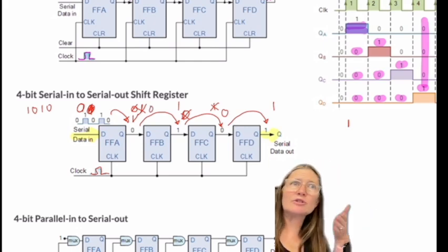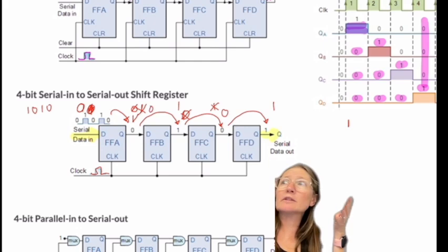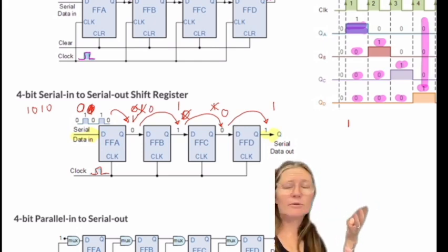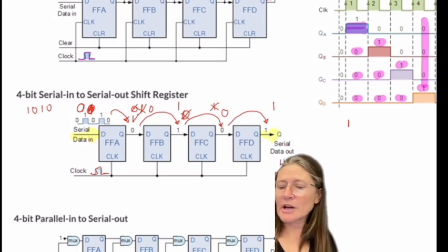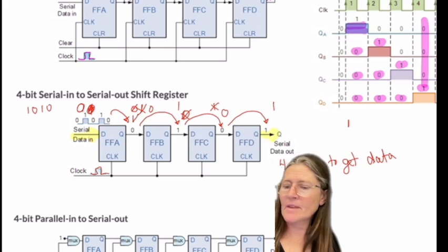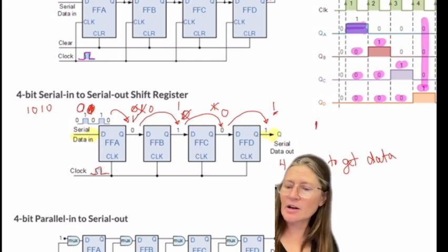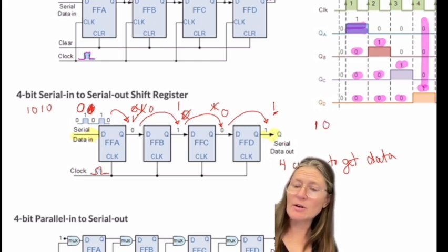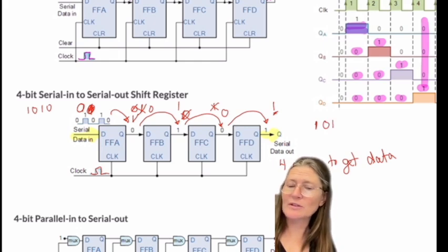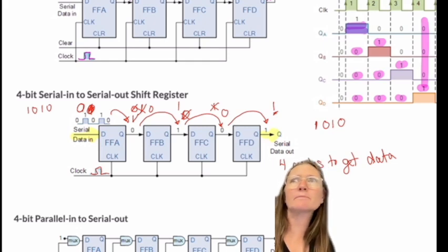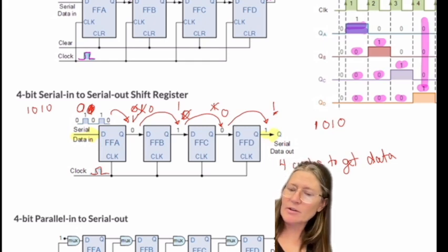So I have in the registers now, after 4 clock cycles, all the right numbers, but now I need to read them out. So 4 cycles to get the data in. And then I can read out. On the 4th one, I read the first one, which is 1. The next clock cycle, which will be 5, I'll read the 0. Next one, I'll read 6, will be this one, and then a 1 for 7. So I'll need 7 clock cycles.